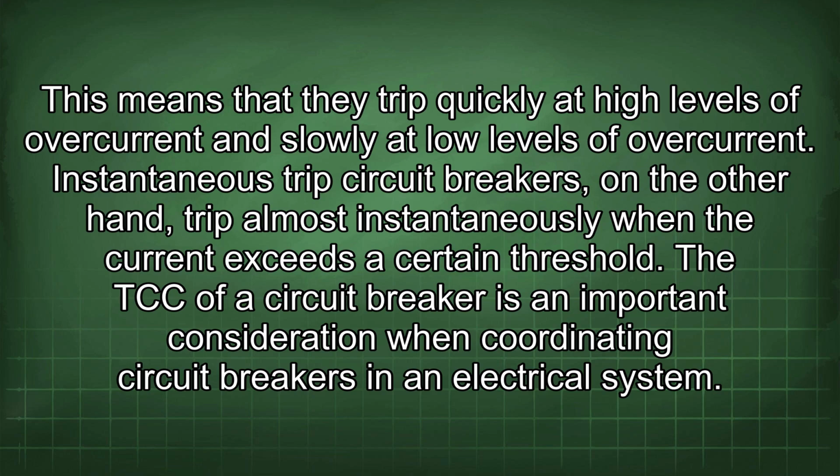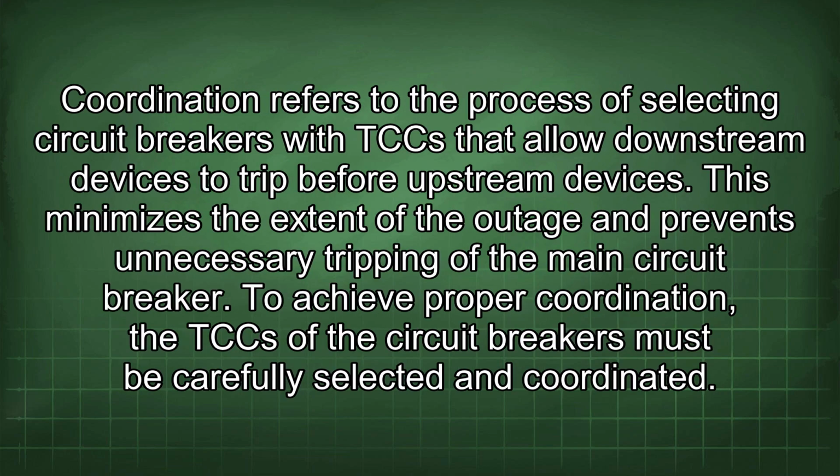The TCC of a circuit breaker is an important consideration when coordinating circuit breakers in an electrical system. Coordination refers to the process of selecting circuit breakers with TCCs that allow downstream devices to trip before upstream devices. This minimizes the extent of the outage and prevents unnecessary tripping of the main circuit breaker.